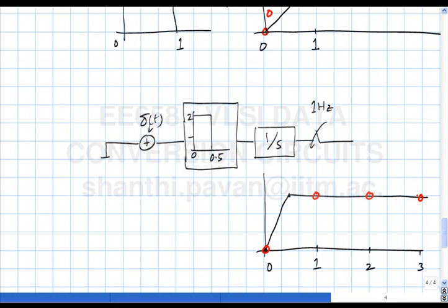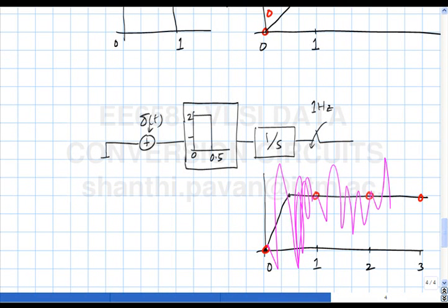So one moral to take away from the story is that there can be any number of continuous time filters which all have the same discrete time equivalent once the outputs are sampled. For instance, you have already seen an example like this. Another thing is in principle nothing prevents me from finding a continuous time filter which does this and then does this. So if I put that continuous time filter in the loop, it would also give me the same NTF. You understand?